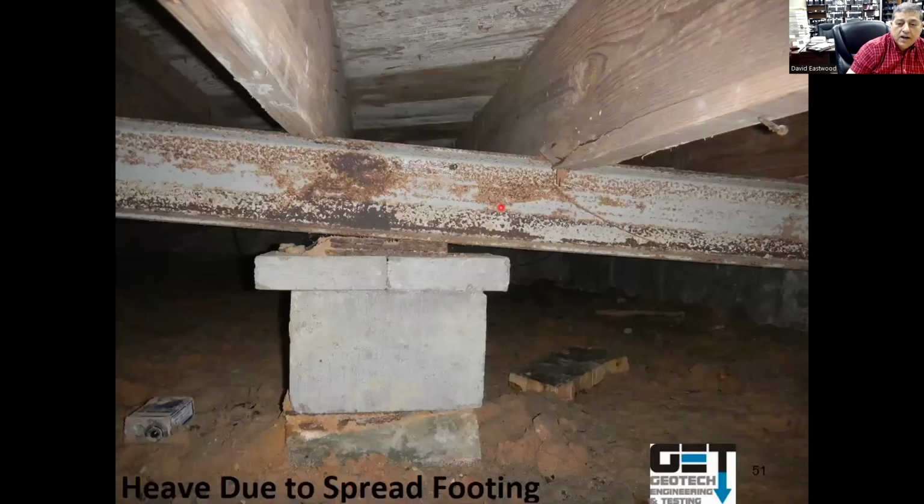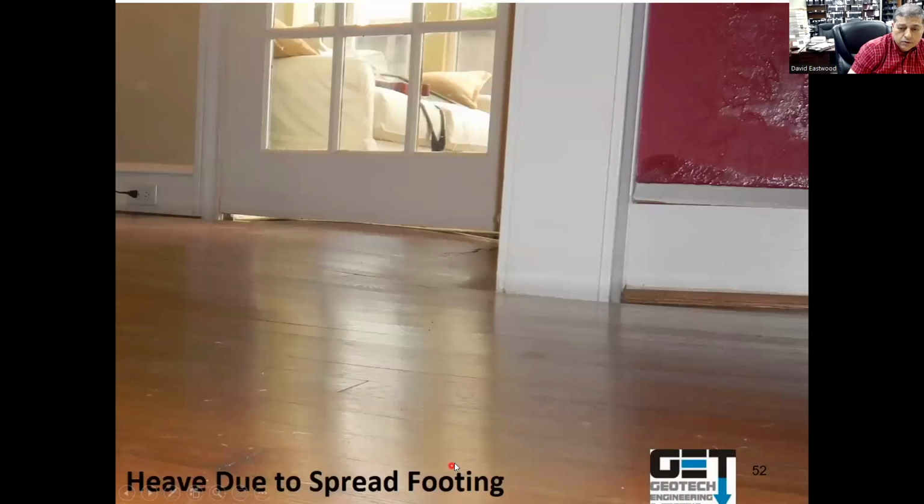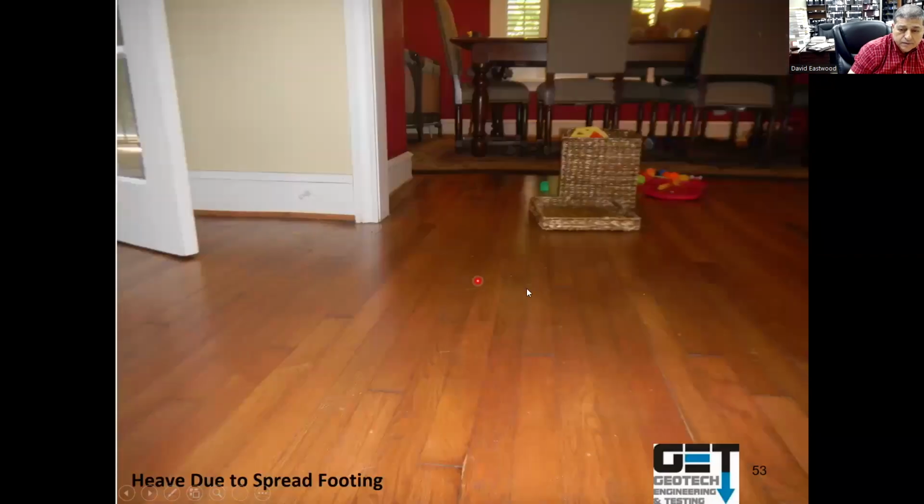Spread footing. These guys were leveling a slab. They put them on a spread footing on top of expansive soils. And the expansive soils heaved up, and you can see all the floor slabs have heaved up where they put the spread footing.